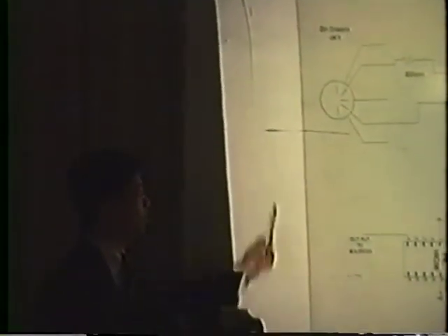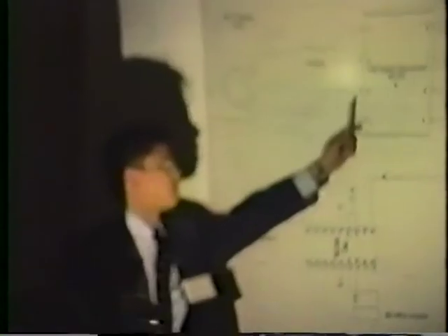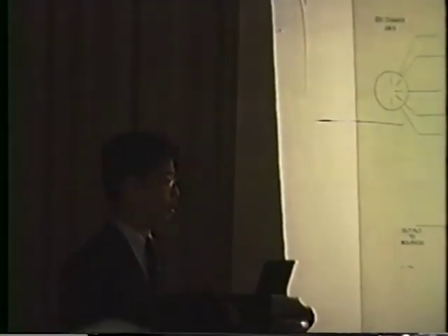Moving on to the control circuit, we have the MIDI input that we send into the optocoupler. The optocoupler is used to isolate the controller circuit from the expensive MIDI devices. The isolated signal is then sent into the PIC chip, which will decide what to do with this signal. Here we use an external oscillator. Even though the PIC chip has an internal oscillator, it has a fairly poor tolerance of up to 28%. Therefore, it is necessary to use a ceramic resonator or a crystal for high-speed transmission, such as in our application.